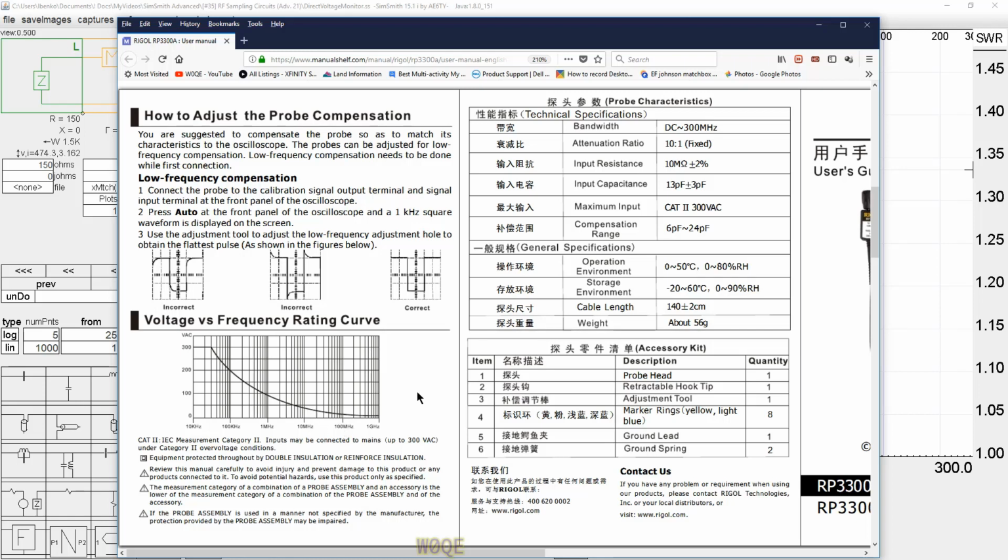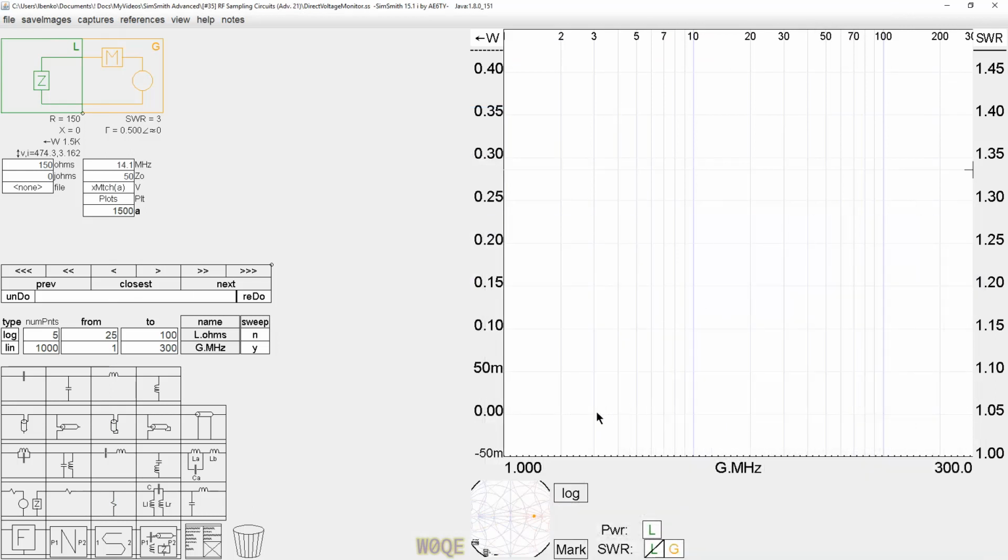So with that being the case, this probe again is inadequate to look at the 470 volt number that we talked about. And it has the same kind of impedance limitations that the Tektronix probe has. All 10X probes are the same kind of construction, so it doesn't have a high enough impedance either. So both of those probes are inadequate, and I suspect just about every probe out there is. There's some special differential probes and active powered probes that can look at high frequencies and still have high impedance, but most of those will not be rated for high voltage also.